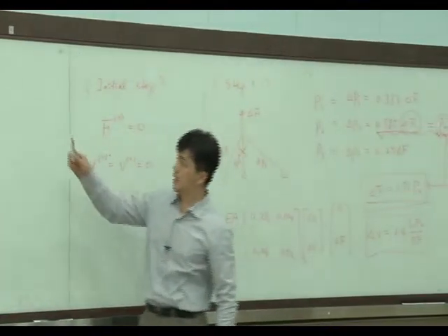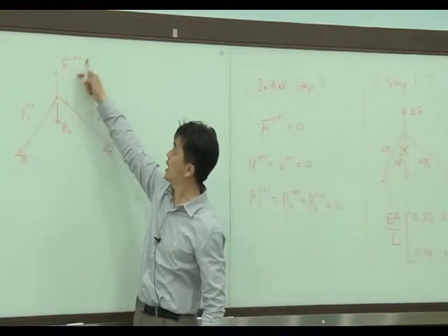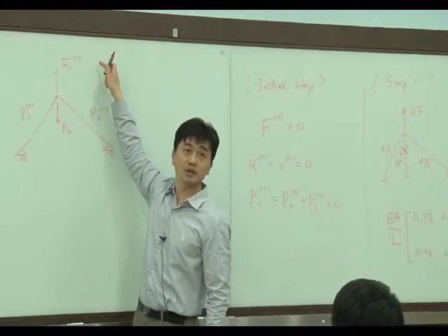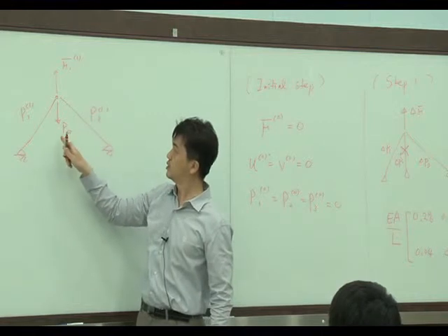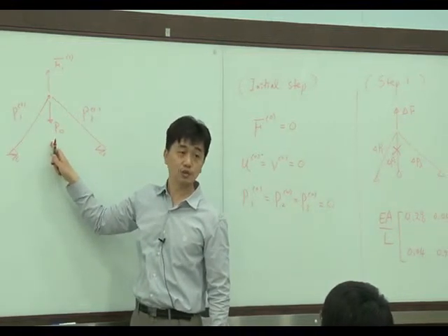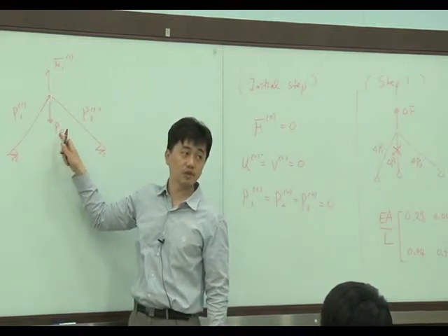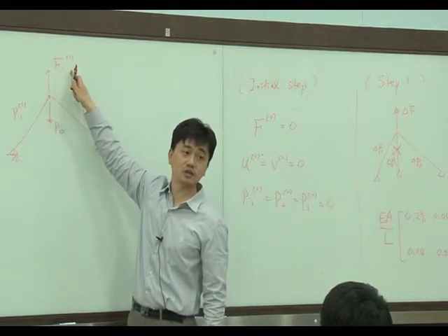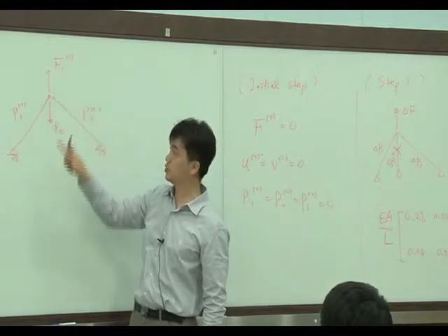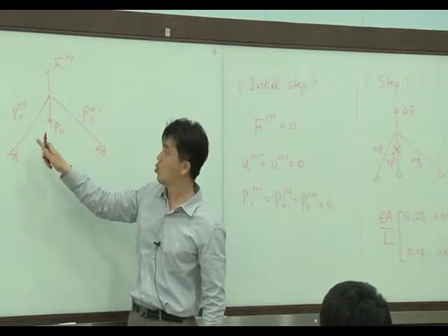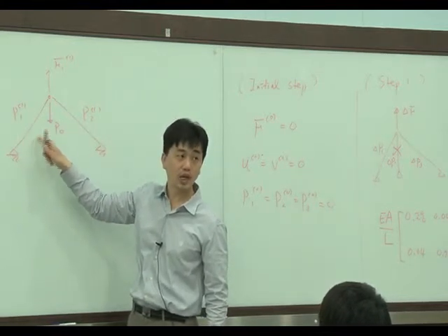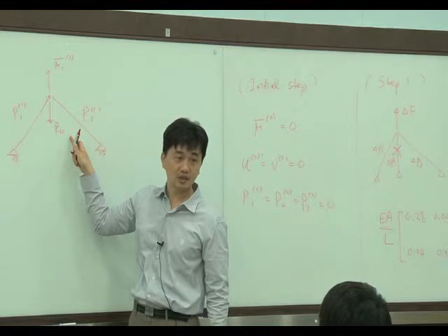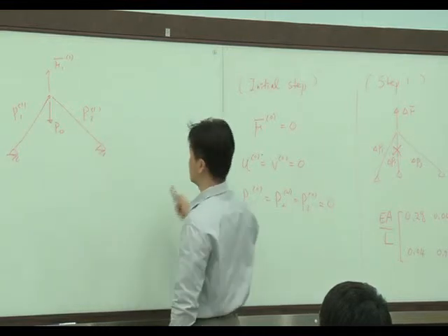So even if I increase the force, adding the force F more, member 2 cannot contribute to support this additional force. So the additional force can be supported by only member 1 and 3. This concept is important.